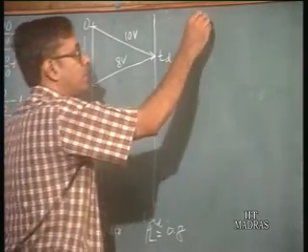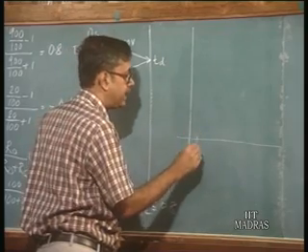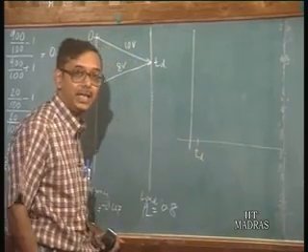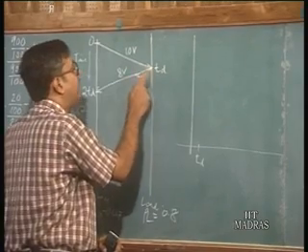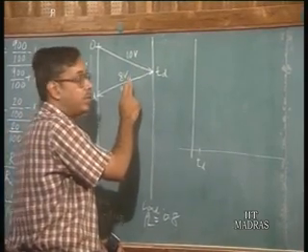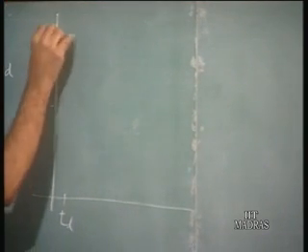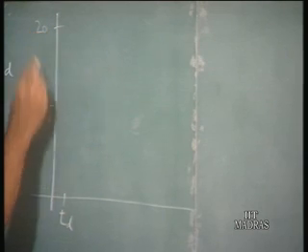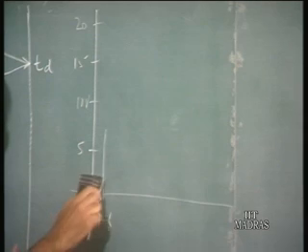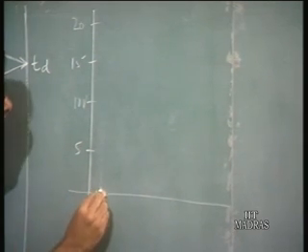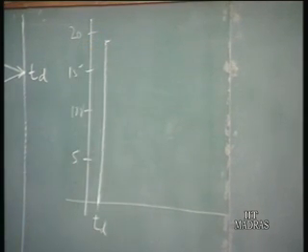If you now observe the waveform at the load end, at Td, which is the delay of the line, the voltage you have is 10 plus 8, which is 18 volts. So if this is say 5, 10, 15, 20 volts, the waveform goes all the way up to 18 volts at t equal to Td.